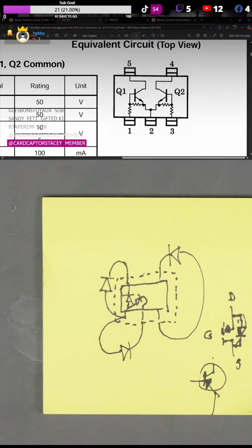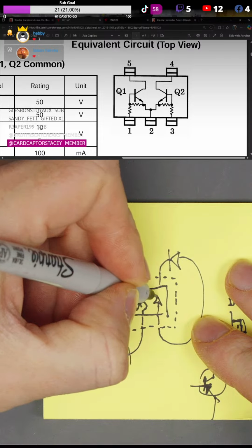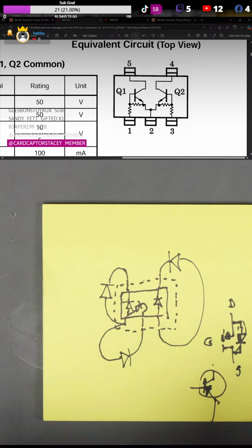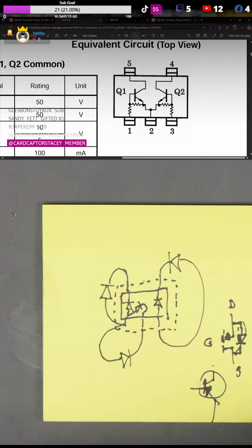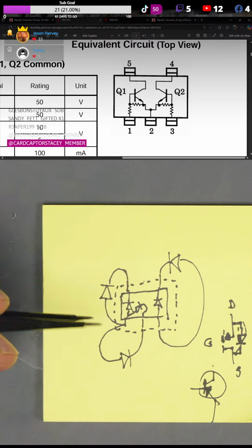But the one going up won't. And the other side has ultimately this going in. Op-amp, I don't think it'll be an op-amp, by the way, because it's got a Q on. An op-amp would normally have a U designator. It's not saying it won't be. I just can't imagine it being an op-amp, and it's part of the voltage regulator circuit.